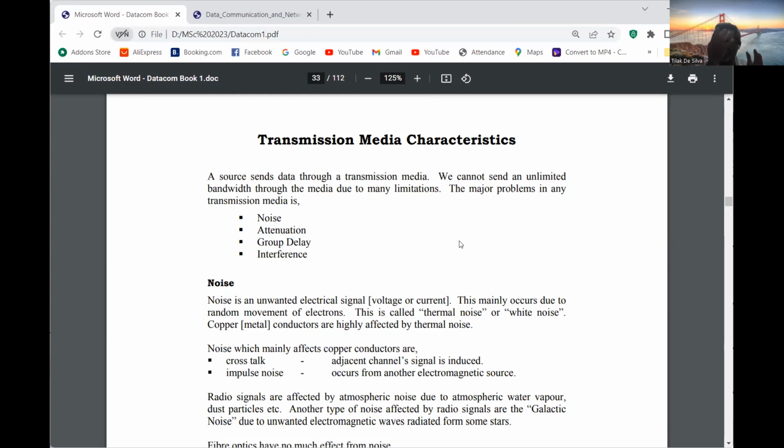So therefore the antenna can be fixed there. You don't have to change the antenna direction, but still the world is not exactly like a globe. So when it is moving in an orbit, there can be a small drifting. It is not completely synchronized with the Earth's rotation, so we have to slightly adjust the direction of the antenna. Is it clear to your question?